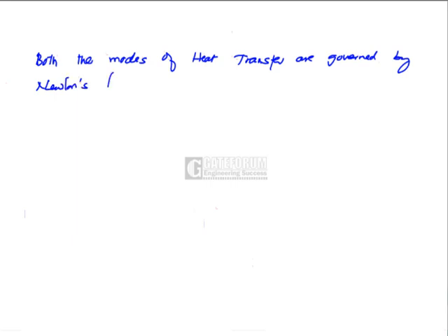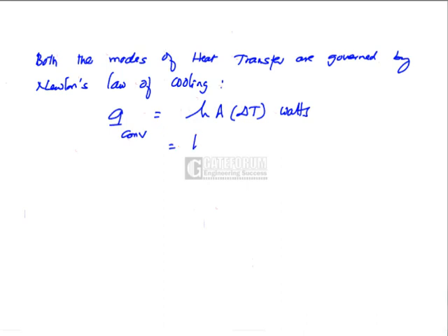Both the modes of heat transfer are governed by Newton's law of cooling, that is, the rate of convection heat transfer is equal to hA delta T, so many watts, or otherwise hA times the temperature of the wall minus the temperature of the fluid.